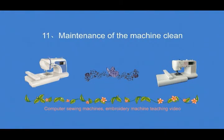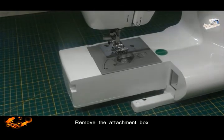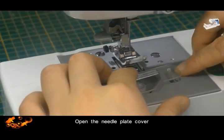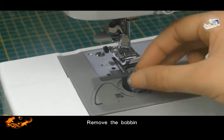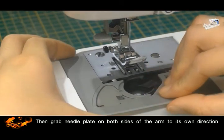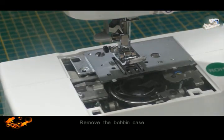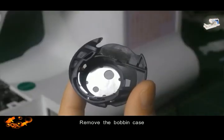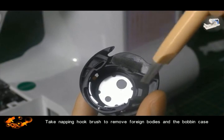11. Maintenance and cleaning of the machine. Shut off the power. Remove the attachment box. Open the needle plate cover. Remove the bobbin. Then grab the needle plate on both sides of the arm and pull it toward yourself. Remove the needle plate arm. Remove the bobbin case. Take the napping hook brush to remove foreign bodies from the bobbin case.